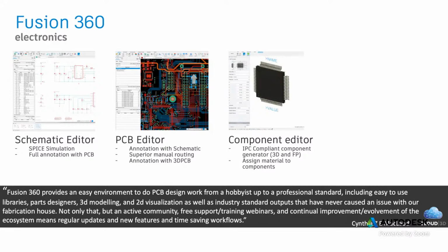Then we have a library editor. We have a really extensive amount of libraries available in Fusion 360, but we don't have them all. But we're doing our best, and we've given manufacturers and some distributors access to our repository. That way they could have control of their own components. Now, we do include a library editor in which building your own component is pretty streamlined and pretty straightforward. And I'll be reviewing that shortly as well.